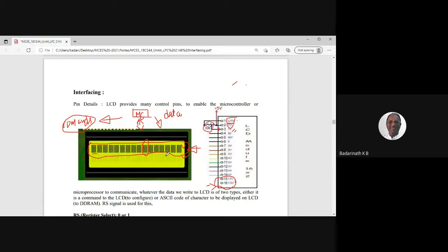That is why the microcontroller should supply the data to the LCD at the speed that is consumable, at the speed required by the LCD, what it can understand. So the rate at which a microcontroller works and the rate at which the LCD works is different. So there should be an understanding. For that, we require what is called status. Status means I'll push one character, let's say character A to be displayed here. Then what will happen? I will read the LCD.